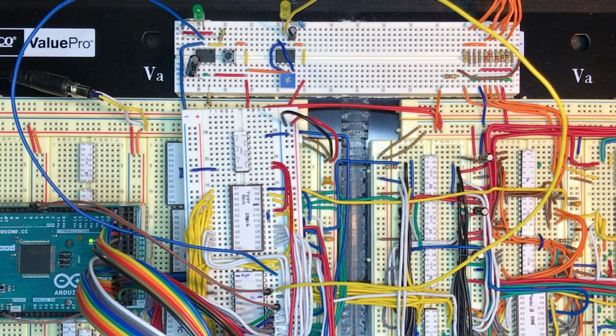The reset pin input of pin 40 is active low, so we need the switch circuit to stay low for at least 2 clock cycles to start the reset sequence. I'm using a 555 timer again to debounce the circuit, that is, to ensure we don't get continual on-off when we press the reset. Not so critical for the slow timer, but it will be important when we use it to reset the full speed version.